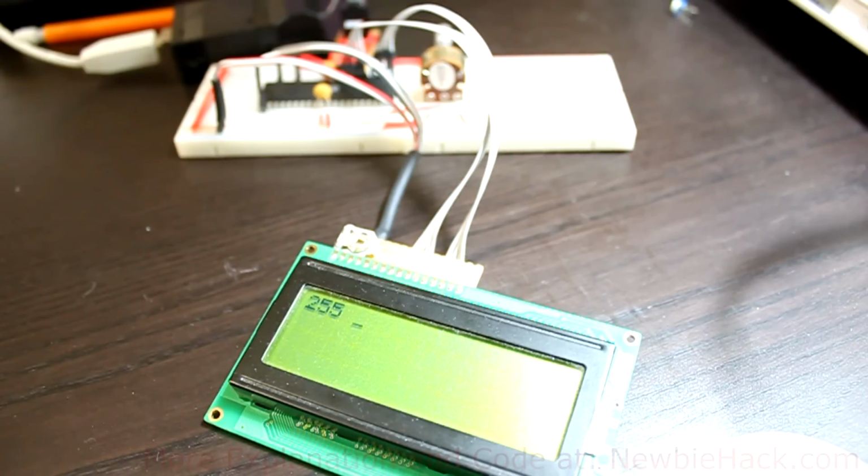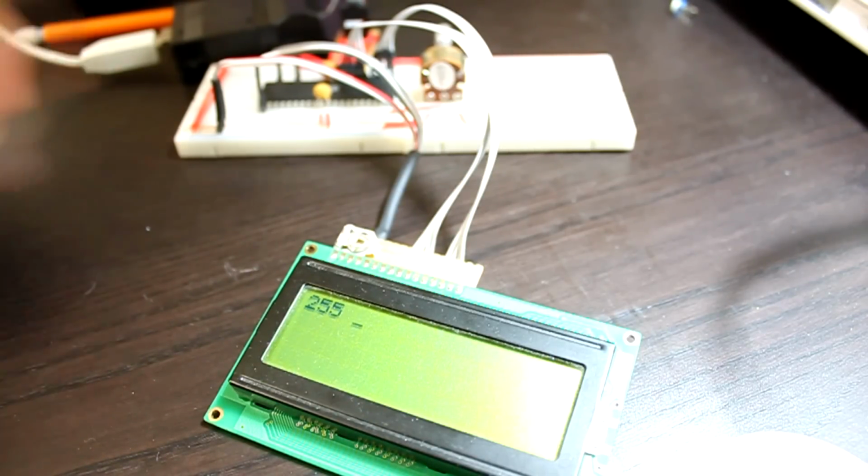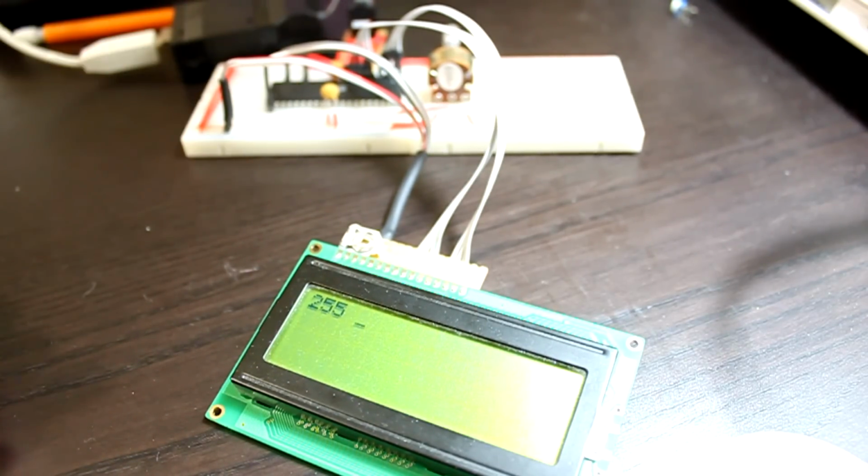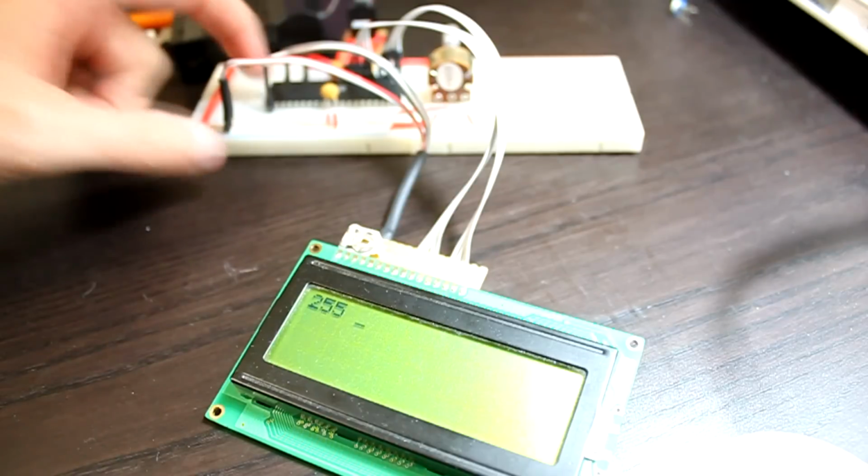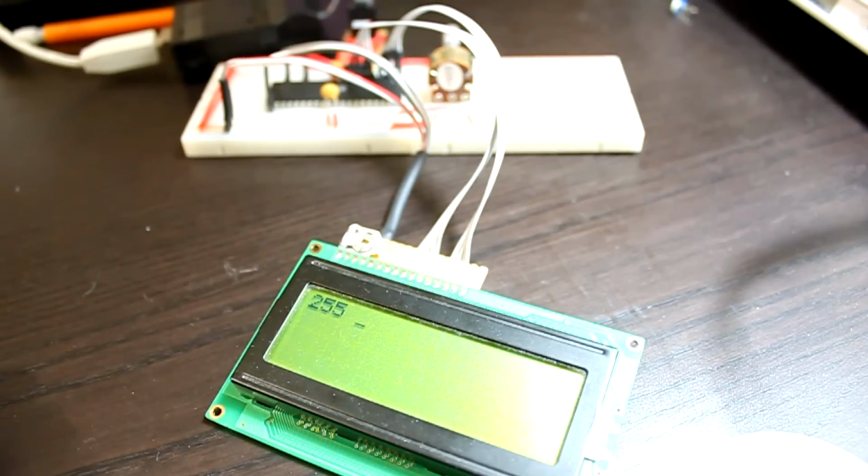So we'll have to tap into their power supply, and essentially make a power supply for them, or we'll need to run the microcontroller at a lower voltage. I'm using the ATmega32. I'll need to switch this one to the 324 so I can go to a lower voltage, and we may be doing that in the next video.